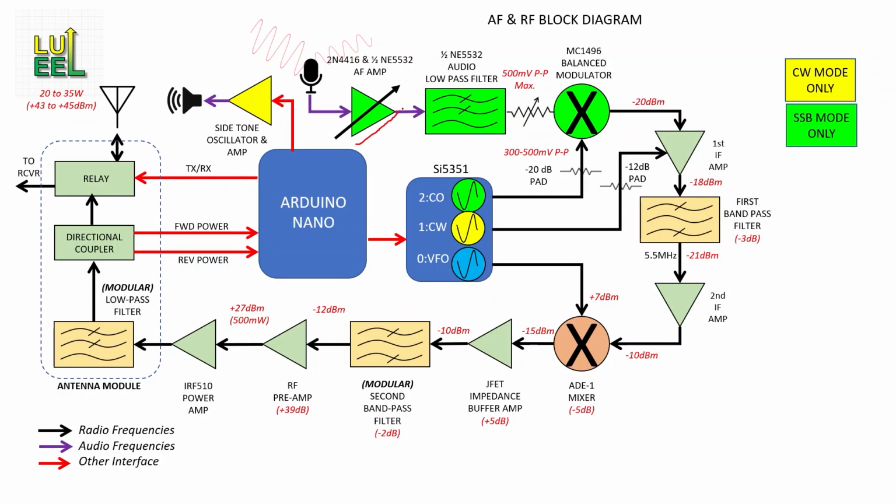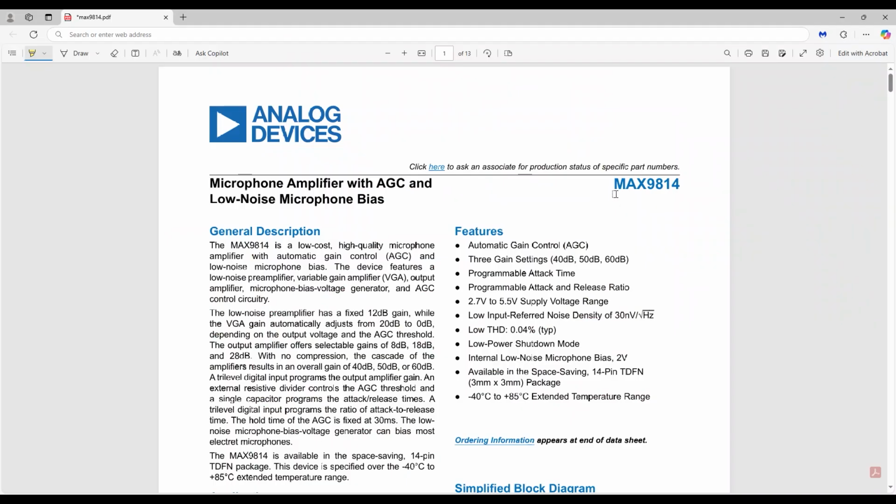What if I had active gain control right here in the first stage, the microphone amplifier? Something that worked in real time to add gain to a weak input, but would quickly reduce gain in reaction to a strong input. That would be really good because then all the downstream stages would always have a predictably strong signal and never be driven into saturation or distortion. Ta-da! There's actually an IC that accomplishes these functions.